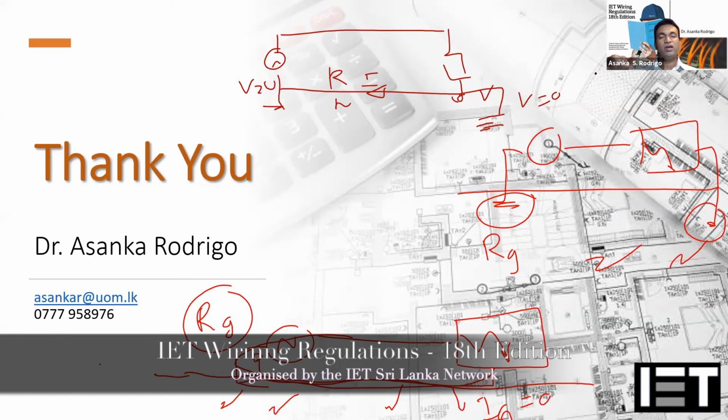Keep in mind, when we say equipotential bonding bar, that does not mean a very small copper connector. It can be a bonding bar running all around the building, and you can connect all these metal parts to that bonding bar, and then connect to the earthing system. Likewise, as per the standard, we have to connect them to the equipotential bonding.